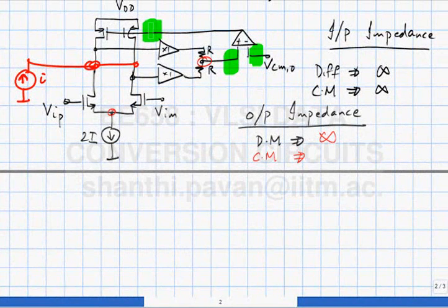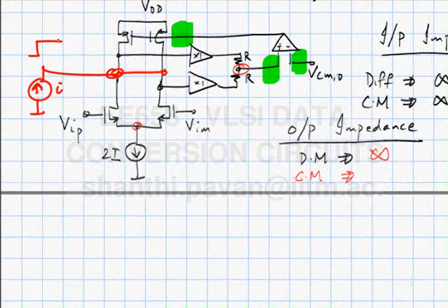So what do you think physically, if you put a real op amp without knowing anything about the details, what kind of voltage would you expect at the output? If I put a pulse current like this, initially what will happen? Initially the potential will rise. During that time, the op-amp is virtually sleeping. Okay, it wakes up and then suddenly goes and kicks the gate. Then what happens? So this is the kind of jump you can expect to see in practice.